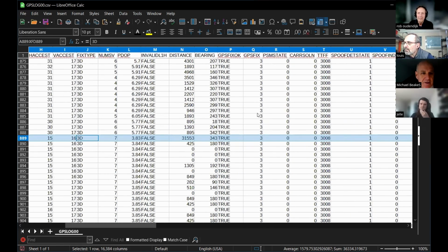The other thing is PDOP at this point. It's nice, it dropped. What I found from this is that there's good news and bad news. The good news is now we have a way to see what's going on. The bad news is that we have to tighten up our constraints of what we consider valid GPS data, and we have to invalidate some of the data that's coming in, based upon a set of criteria.